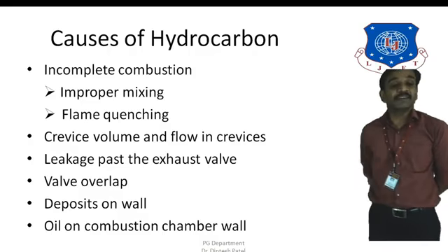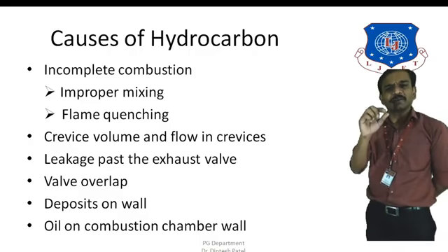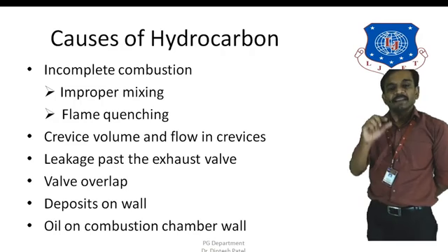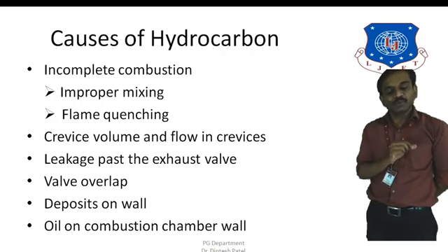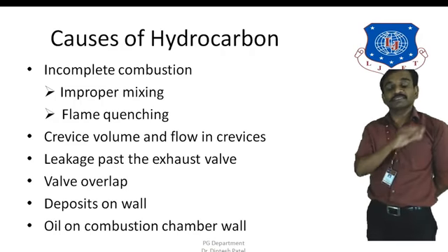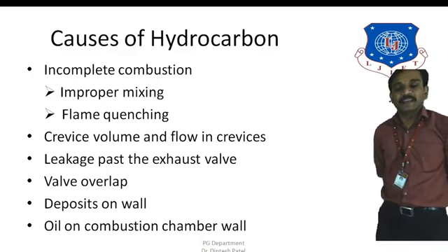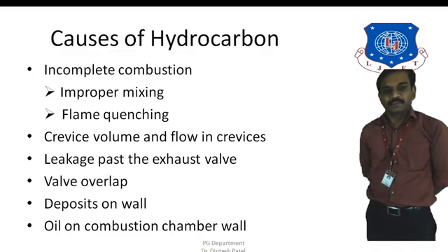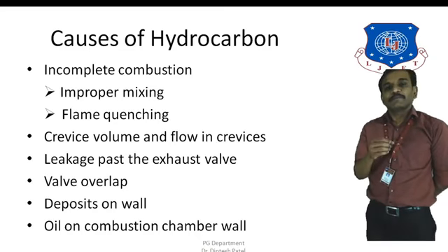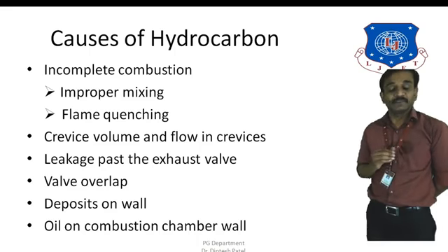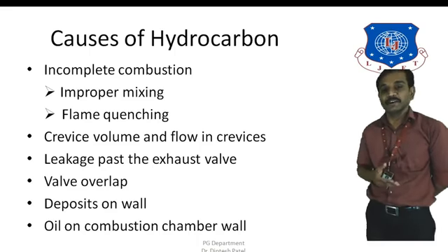Then the fourth one is the valve overlap. You know that both valves remain open for a certain period of time. So during that time, certain portions of the fuel would escape from the combustion chamber through the inlet valve. A few fluid particles also escape from the exhaust valve during the valve overlap and they would remain unburned.